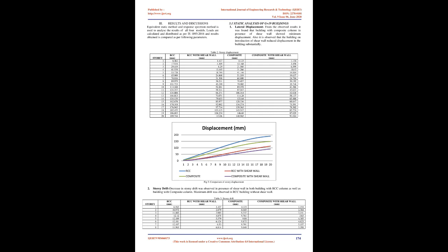For high-rise buildings, beam and column sizes are very heavy and requirement of steel is large, because of which there is a lot of congestion at the joints, making it difficult to vibrate concrete at the joints, and also the displacement is quite heavy. In India most of the buildings are low-rise. So, RCC members are used widely as it is easy to construct and is economical.